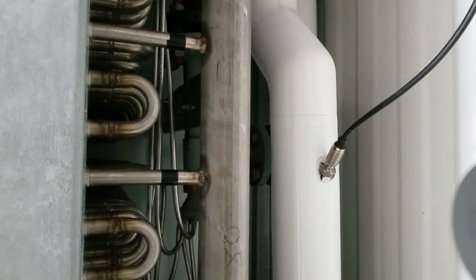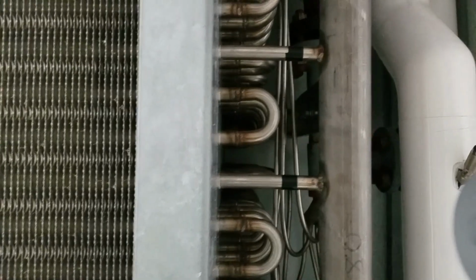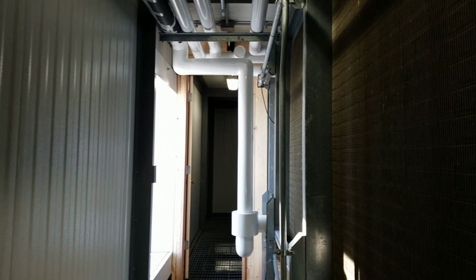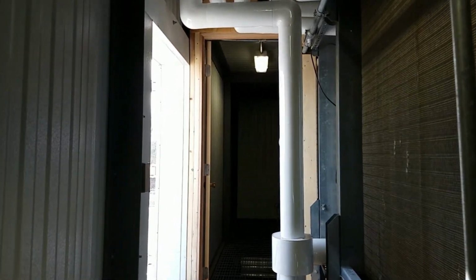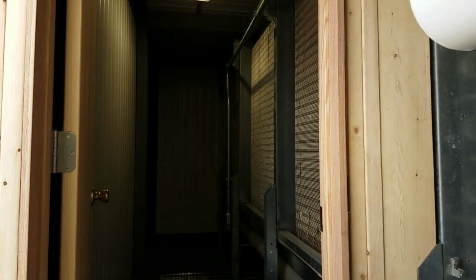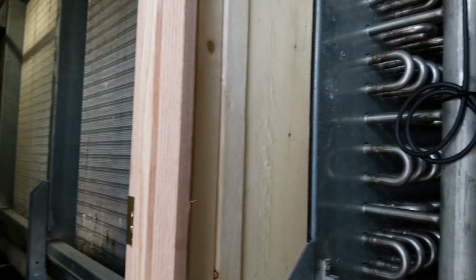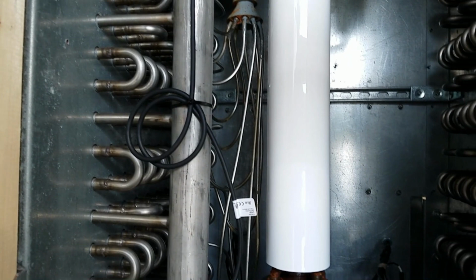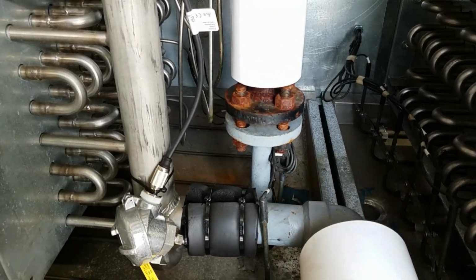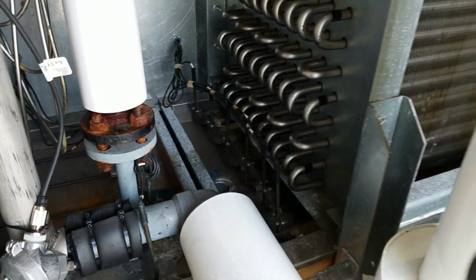We are now in the supply side of our evap room. This is where the CO2 is injected into our two large coils. This space is usually very cold, but we are currently not running. We can perform hot gas defrost on these coils, but we've partitioned the rooms to make that job slightly easier. We have electric defrost in our pans to facilitate in removing moisture.